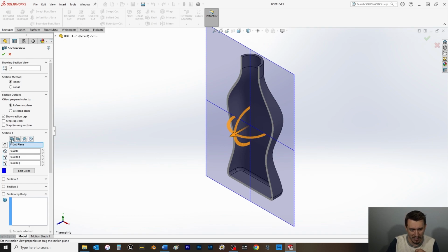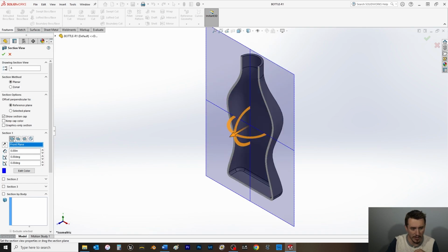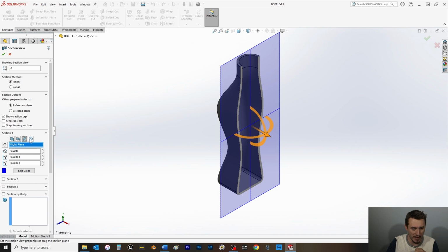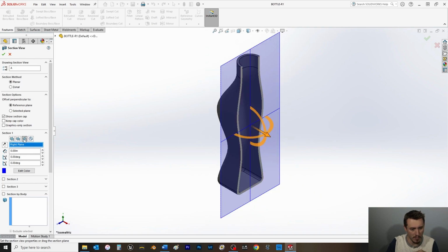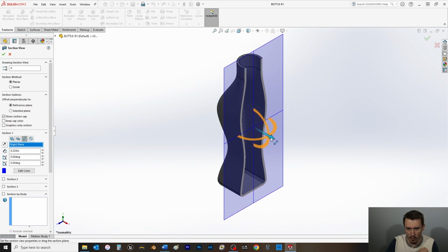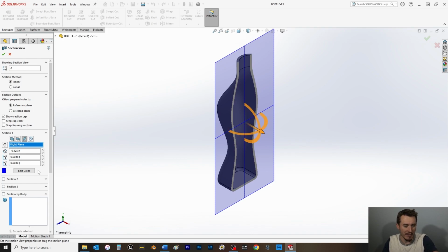Another thing they want to highlight is the fact that you can of course change the way the section view is from either front, top plane, right plane, and newer are axis plane choices as well. But even within each sectional view type, whether it's front, top, right, axis is a little different, and we're not going to cover that in this particular section. But you can take this arrow here and drag back and forth to change what part is actually in fact sectioned, and it's customized.